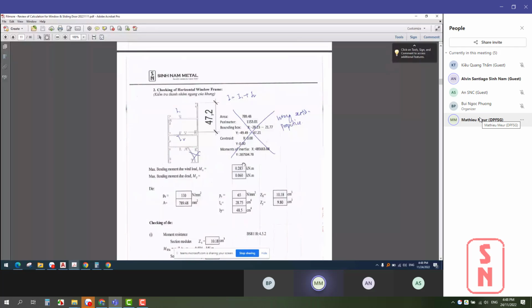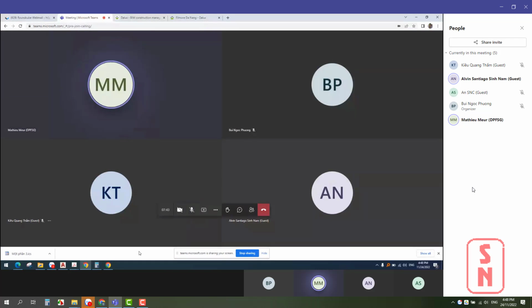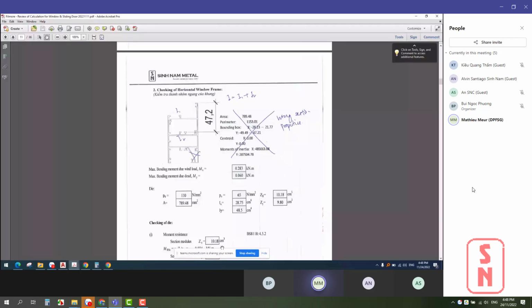So it can slide, and therefore there is no shear transfer between the beading and the, call it, the transom or the mullion, whatever it is. This one is a horizontal frame, let's say. I understand. So because there's no shear transfer, you cannot consider it a monolithic component.